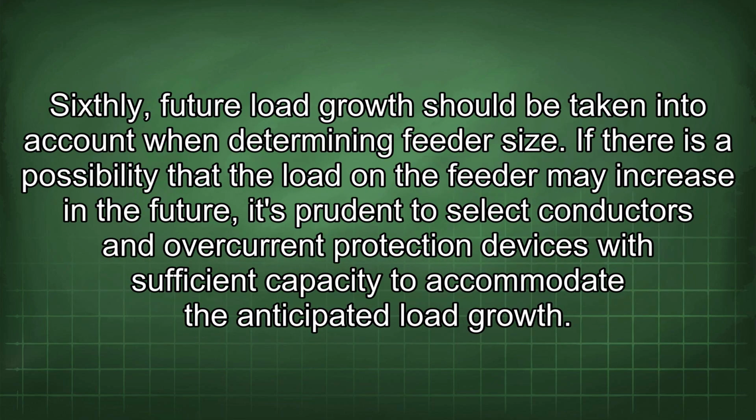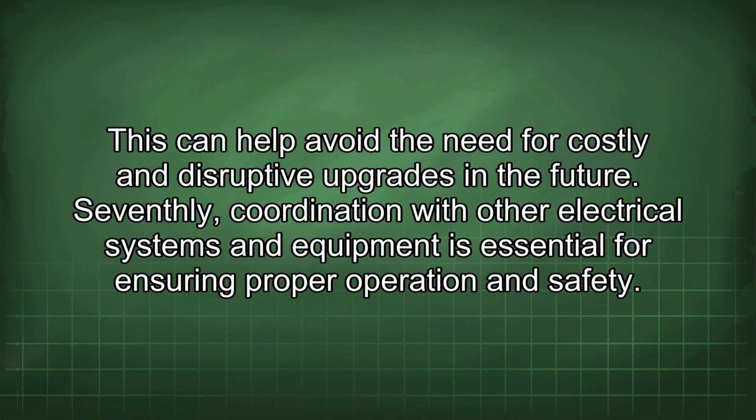Sixthly, future load growth should be taken into account when determining feeder size. If there is a possibility that the load on the feeder may increase in the future, it's prudent to select conductors and overcurrent protection devices with sufficient capacity to accommodate the anticipated load growth. This can help avoid the need for costly and disruptive upgrades in the future.